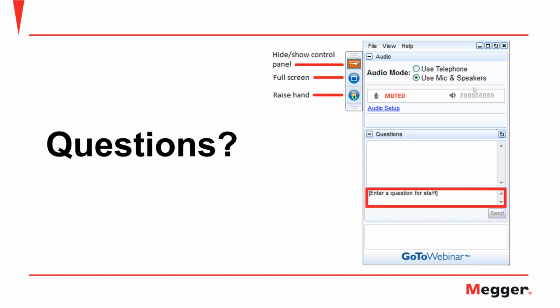And you do not have to go line of sight. You can run your potential probe off at other angles. And it seems to me, and this is where I'm coming up short in my knowledge, and I really should explore this, I think 90 degrees is the one that you don't want to use.